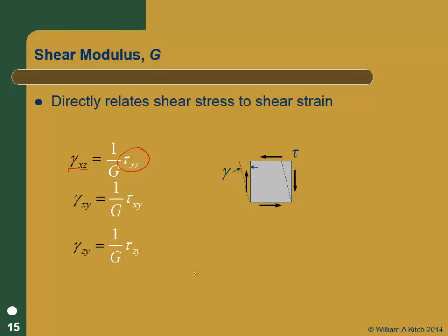For instance, we do a lot of things with shear wave propagation. Anybody who's done earthquake engineering, right? We want to know about the shear wave propagation. Well, the shear waves propagate proportional to the shear modulus. The P waves, which is the first wave that you feel from an earthquake, propagate proportional to the bulk modulus because it's happening in an environment where there's just normal stress change.